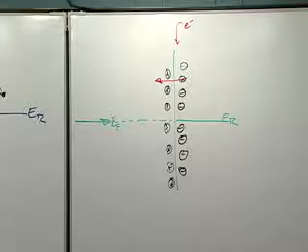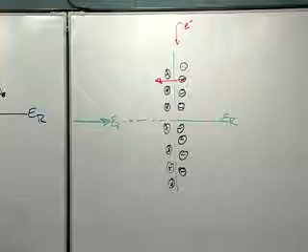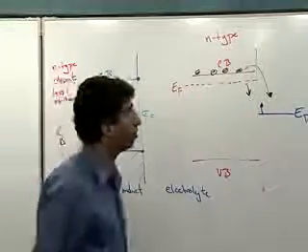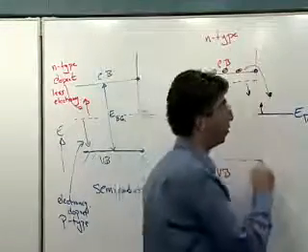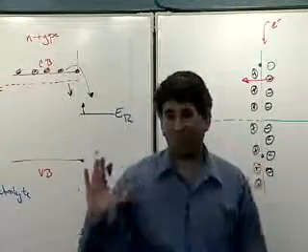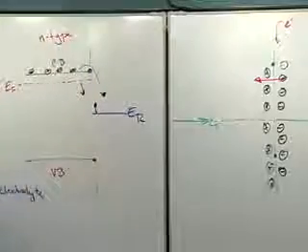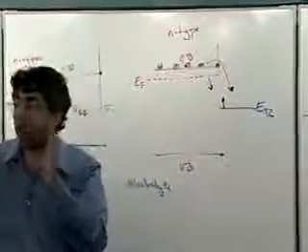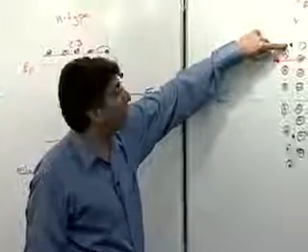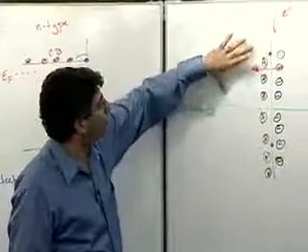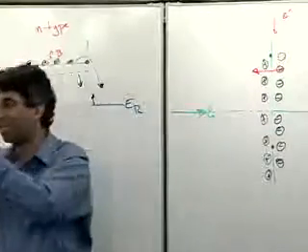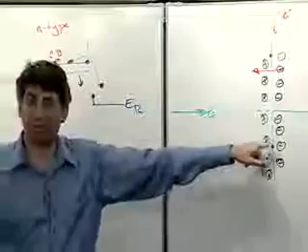Okay, that is, we are going to say that the edges of the conduction band and valence band are fixed at the semiconductor electrolyte interface. They have to be fixed. This is not arbitrary, for one very good reason. The interface is a line, a geometric line, and so this is one point on the line. It has a potential which is determined both by the semiconductor and by the electrolyte. But it's one point, so there can only be one potential associated with it. Same thing down here.